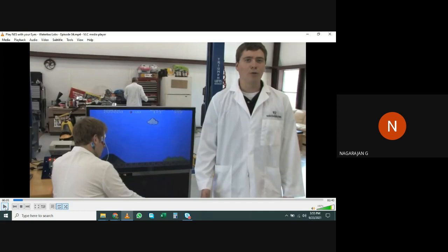But here, if you see, they have used LabVIEW FPGA, okay, they have used a single board RIO, which is a family of RIO hardware, and they have used LabVIEW FPGA to have control. They are going to place sensors near our eyes, and we know whenever the eye moves it gets polarized and generates some voltage.